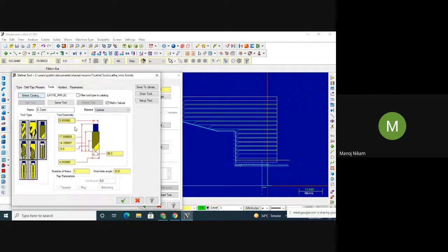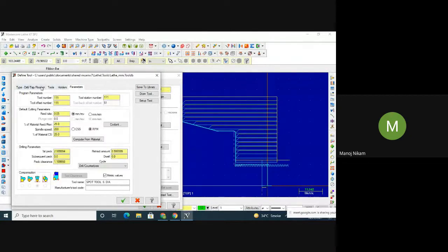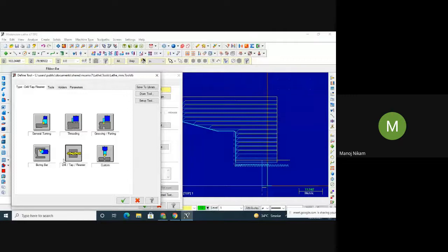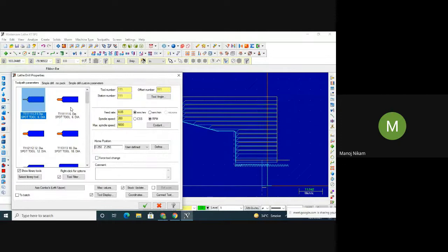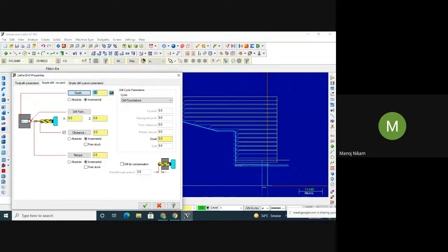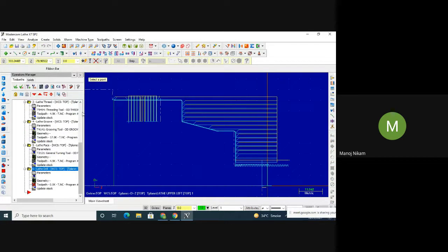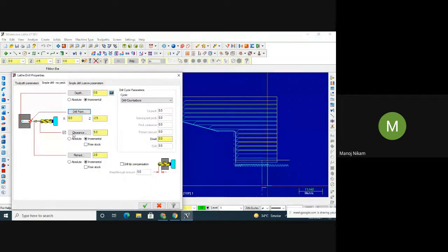You can select the tool, and here also you can modify its diameter, like 2.5 का अगर diameter चाहिए वो आप change कर सकते हो. You can change the other properties also if you want, but I just want the simple drill operation. जिसका मैंने 2.5 mm dimension रखा है. Okay, so where you want the drill, where it should be your drill point. So it's asking for the drill point. So click on drill point, click where you want to do drill, यहाँ पे चाहिए, और वो कहाँ तक करना है, the end depth point, और depth मेरे को चाहिए यहाँ तक, it's -12.5. Okay, that's it. Okay, click.